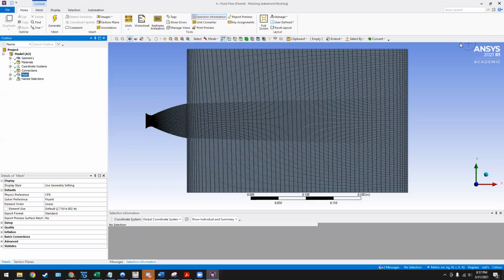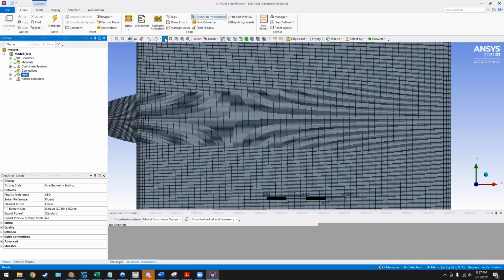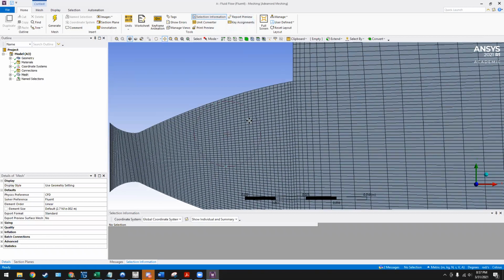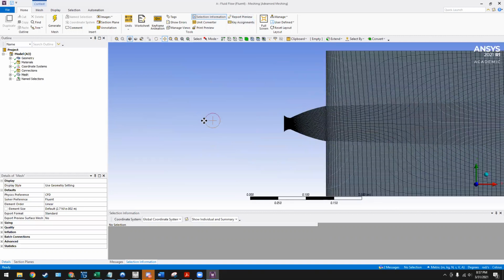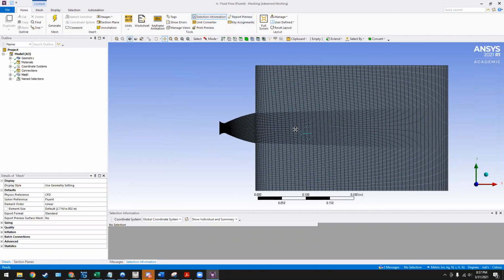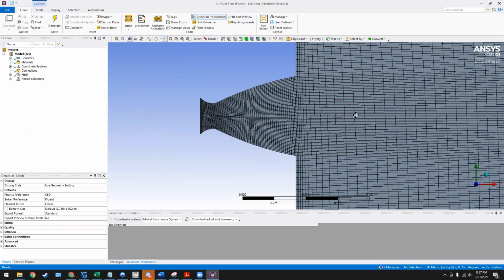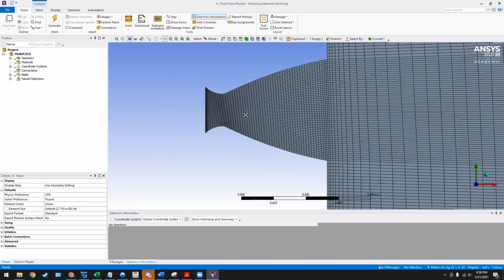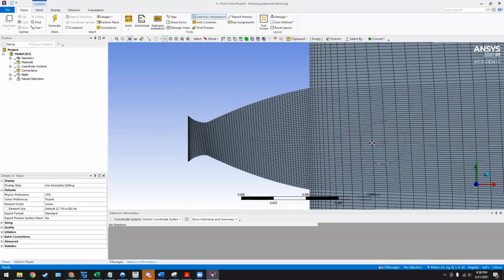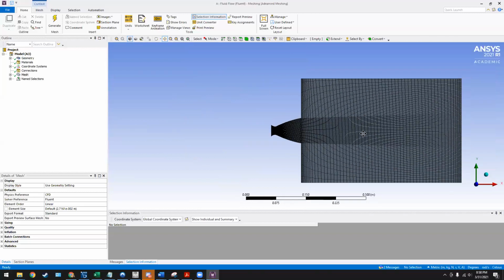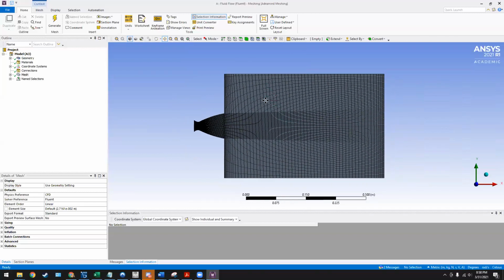My round nozzle was created similarly to my personalized nozzle. I made sure to do this first in SpaceClaim, and this was different than the Design Modeler in the sense that it was just a different building tool. I was able to convert the MathCAD file to a text file and then upload those coordinates and then reflect them across an x-axis to have one big nozzle shown here.